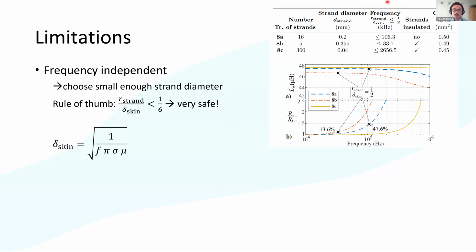In particular, the wires differ in the strand diameter, and the strands are insulated. Some of them are insulated and some of them are not. The copper area is as close as possible, but of course you will never find 2 different wires that are actually the same, which is why we also get a small difference in those leakage inductances.